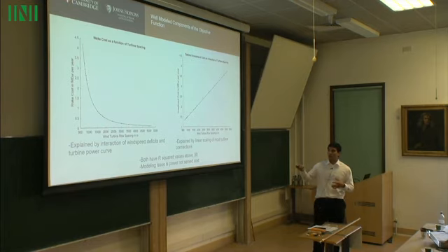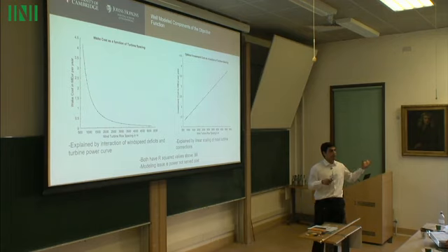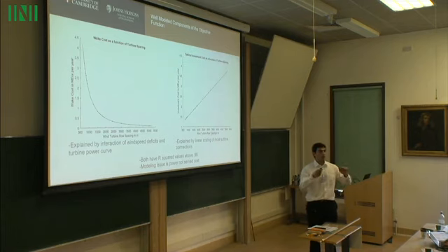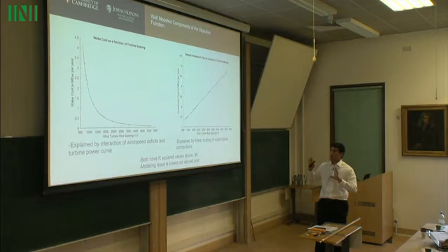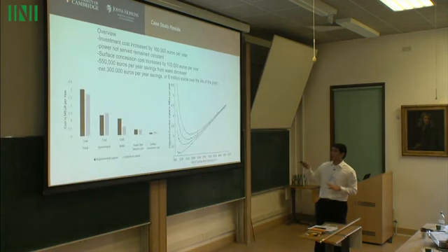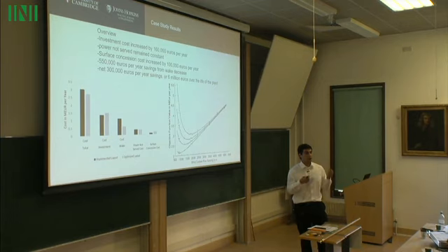And in practice, the reason why we thought this was an exponential decay model was understanding the interactions between the power curves that say, okay, if this wind is coming in at this velocity, this is the amount of power that's output, in combination with the way that the wake effect decreases if you spread turbines further and further apart. And in practice, both of these components of the objective function were very well modeled in exactly the way that we expected them to. So we were able to create these powerful economic curves where we understood this continuous space of layouts based on only discrete finite observations of this specific instance of the layout, this specific instance of the layout, and this specific instance of the layout.